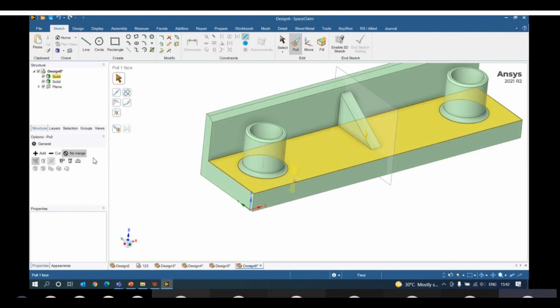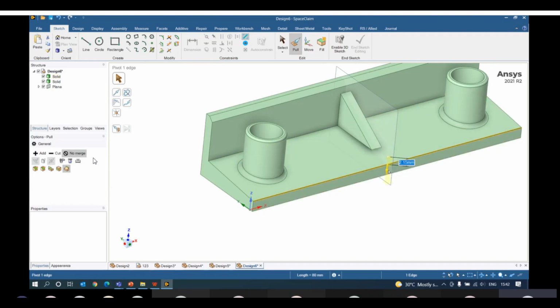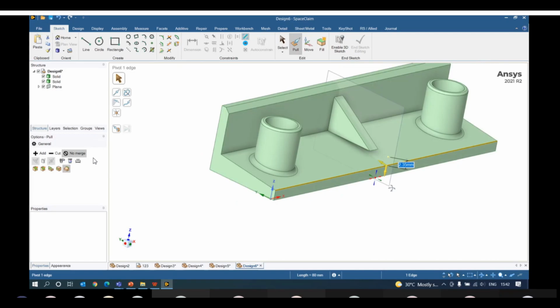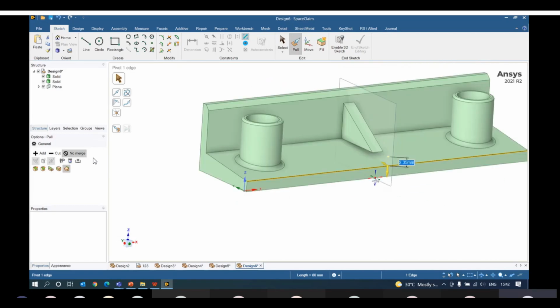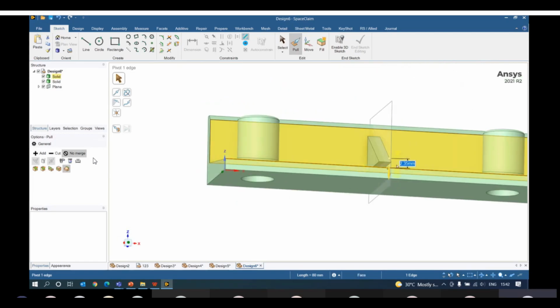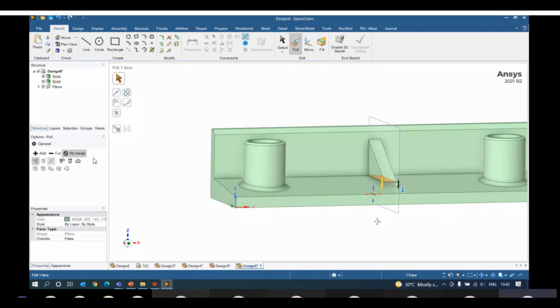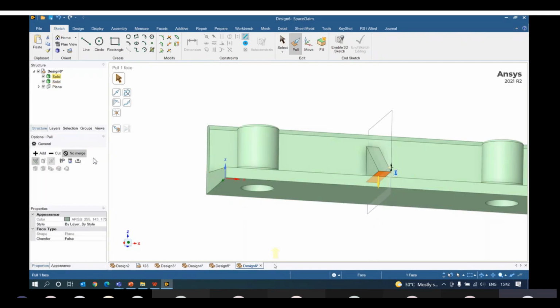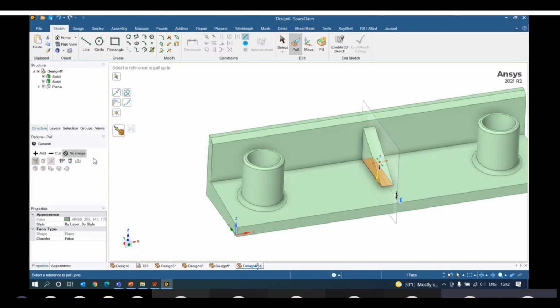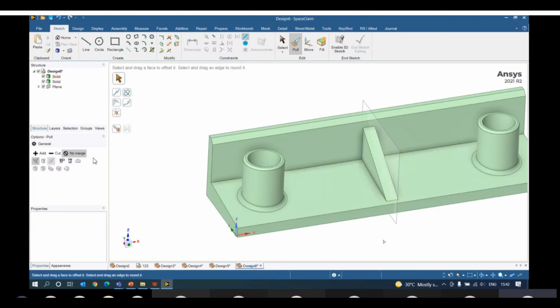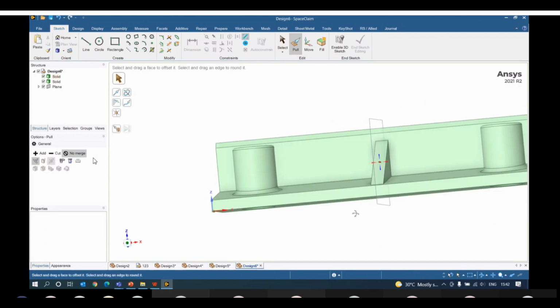And then if you wish, you can also have a pivot. Let's say I want to make some modification like this. So you can see your geometry is modified. And suppose the surface you want to make it touch, select the internal surface and say up to selected surface. So now this is modified, right?